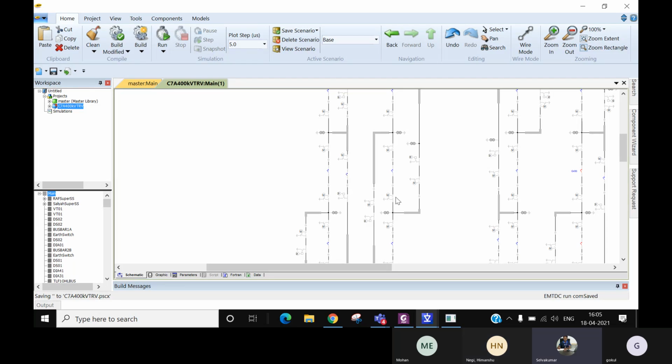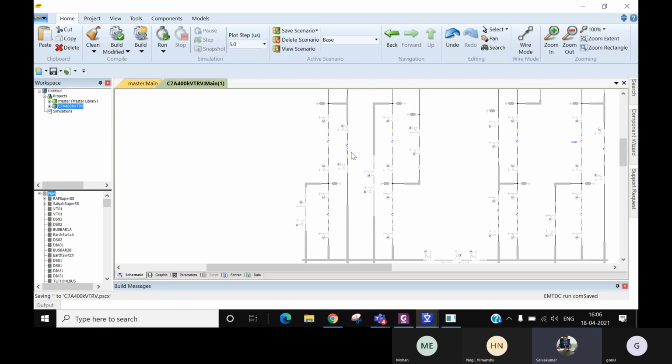But still, despite the breaker getting damaged, you may need to safeguard your equipment, which is a reactor. Even if the breaker goes, okay, I will replace that breaker at some cost. But the reactor is extremely expensive. So to avoid that, you may need a surge arrestor or a surge suppressor at the reactor terminal, if the voltage goes beyond that value. But without a restrike, your surge arrestor at the reactor terminal is not going to help you in reducing TRV.